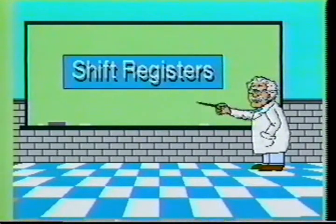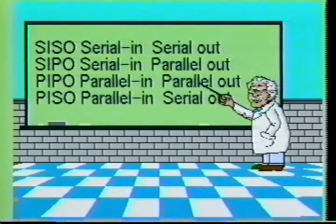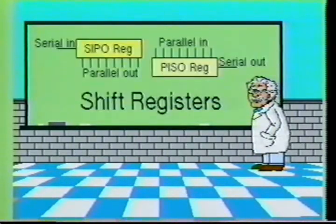The most common storage register is the shift register. Shift registers are generally classified by the method in which the data inputs and outputs to and from the unit. The most common shift registers found are the serial in, serial out, serial in, parallel out, parallel in, parallel out, and parallel in, serial out. Shift registers may be used to convert serial data into parallel data, or to convert parallel data into serial data.